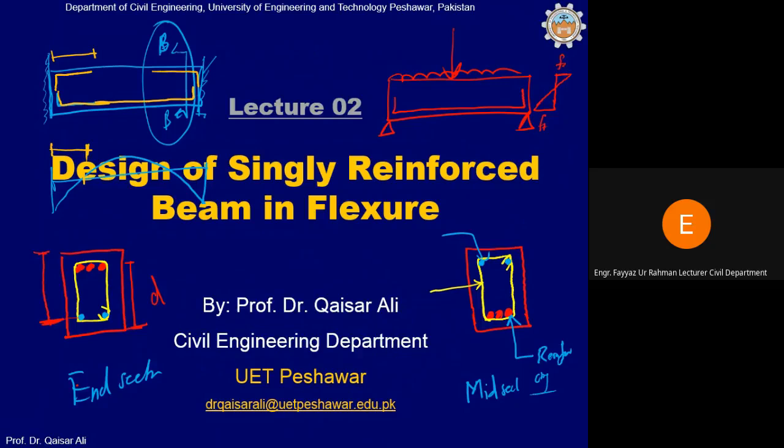Because we defined D as distance from the extreme compression fiber. So in this case, the extreme compression fiber is this one, the lower portion. So distance from extreme compression fiber to the centroid of tensile reinforcement. And in this case, you know that the tensile reinforcement is given in the top portion of the beam. Clear? So that is why in this case, this will be your D.